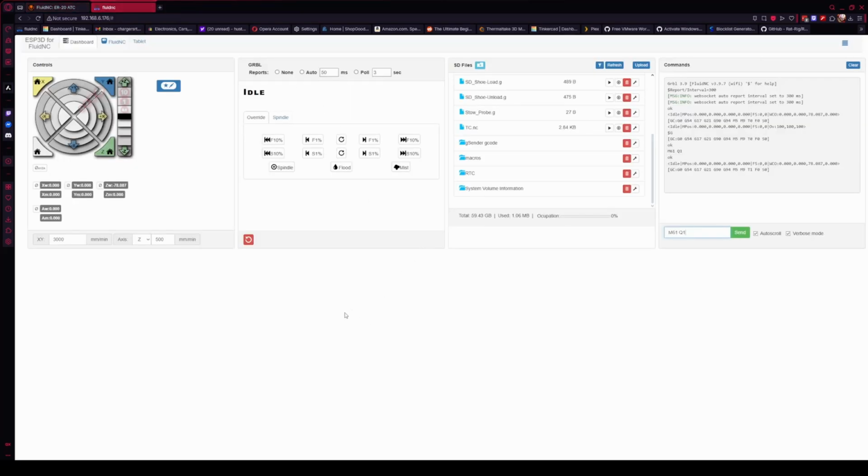Everything else is pretty much the same. The program does work. You can connect your machine if you don't have the WebUI loaded. I use OpenBuild's control. I've used that before for running the machine. I also use Universal G-Code Sender for certain things. Universal G-Code Sender allows you to probe hole centers and find the center position of a hole. It has surface scanning, which means if you wanted to probe 9 different points on the top of a workpiece and get those calculations, you can do that.